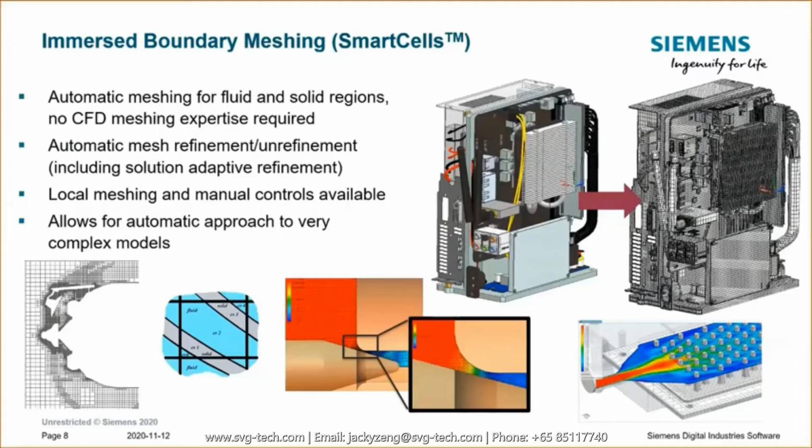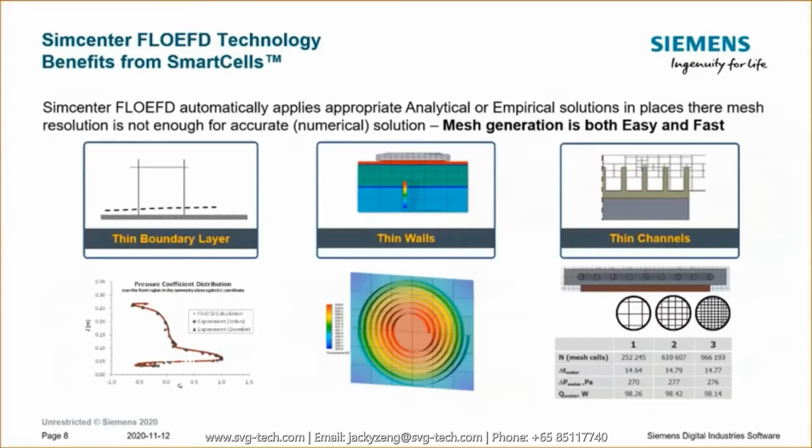Now, if you do become a more experienced user and you want to invoke some meshing control, you can. It is available, certainly. So I don't want to give the impression that it's just this black box approach. It's flexible, but the real power of it is being able to just take an unsimplified CAD model and, with very few inputs, get a mesh very quickly, which is a big time saver and gets rid of a big bottleneck in doing CFD generally.